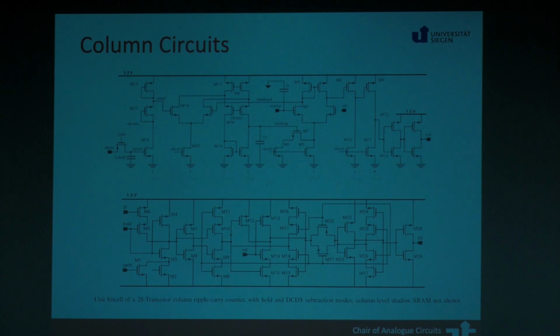If I have 8 bits, I need 8 SRAMs to store the data value. Each SRAM will be 6 transistors, so you already have 48 transistors just for memory. I cannot put a DRAM here, it will not be advisable, so we all go with SRAMs. And so the column pixel circuitry often takes longer to design. Okay. Good. Any question on the circuit aspect of it?